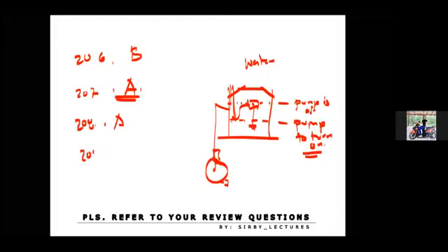Number 209. In order for water not to overflow in the water tank of a poultry farm, what would you recommend as an agricultural engineer? Letter A. Install a float switch to shut off and on the pump. Letter B. Install a motor controller to limit the pumping speed. Letter C. Close the valve manually. Letter D. Close the tank when it's full. Okay, so for letter B, if you install a motor controller speed, then probably it would affect your pumping capacity or your head capacity. So this is not an answer. For letter C, close the valve manually.